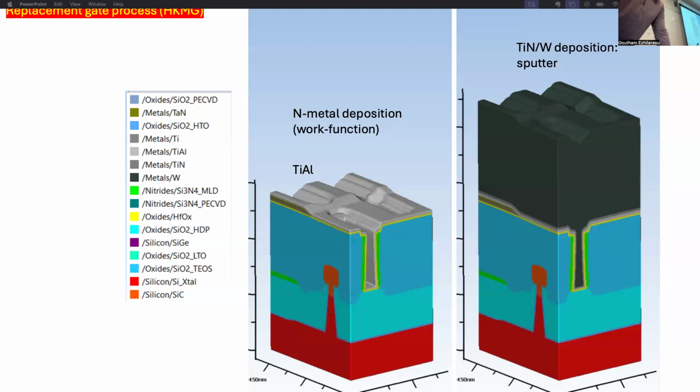In the gate, we don't have any metallic contact to the semiconductor. Why do we care about the work function? For the gate, what do you mean? This gate, the metal touches the semiconductor through the oxide. Yes, there's a hafnium oxide between the metal and the semiconductor. Because of that layer, the metal doesn't directly touch the semiconductor. It's a MOS capacitor actually. See, when you make the transistor, right, there's always this oxide between the gate and the silicon.